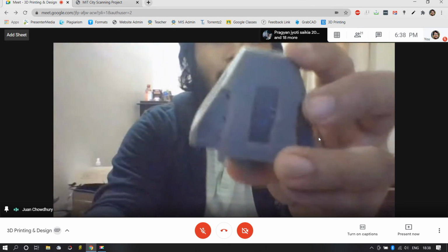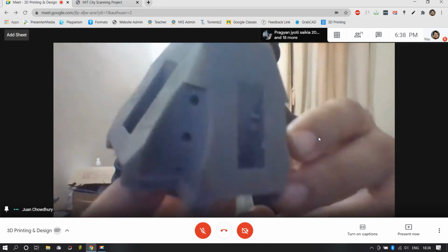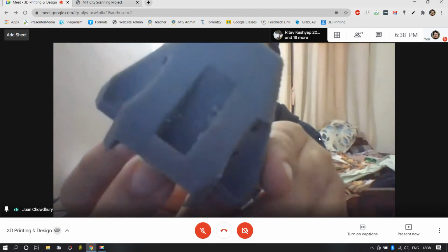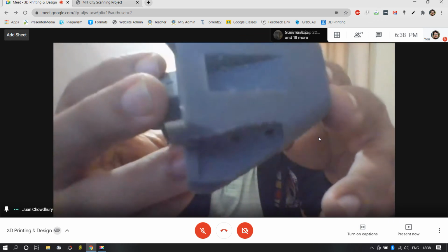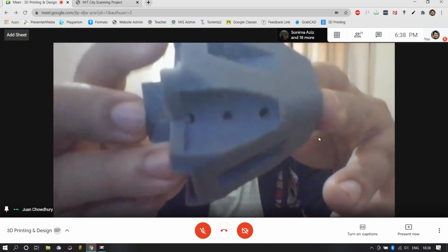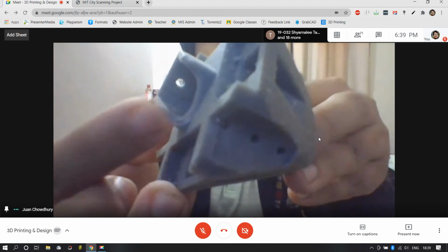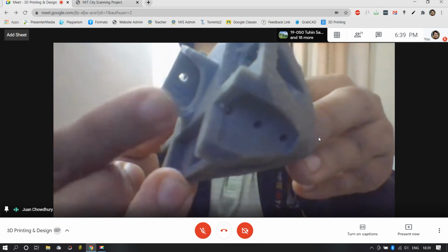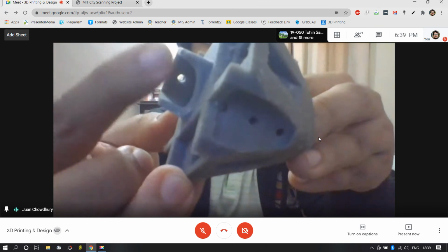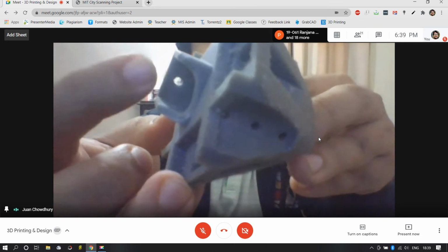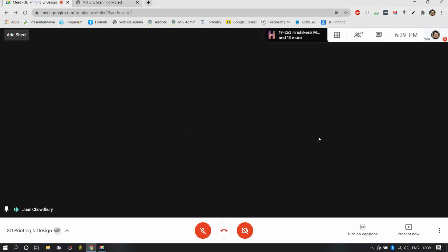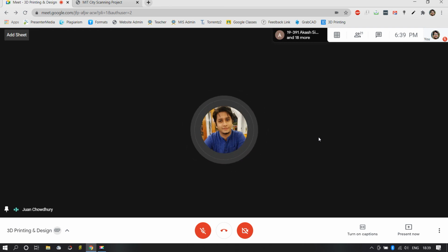We went ahead and modified with the SLA, and we got this rather carved out, lightweight 3D printed part. Upon operation, it was evident that we were facing a problem with certain breakage when operating in the machine. Can you see how it broke down? Right over here. So we had to go ahead and design it at a greater thickness, and that was only when it was known. So a lot of design iterations, and finally we had our complete shuttle, which is now assembled.